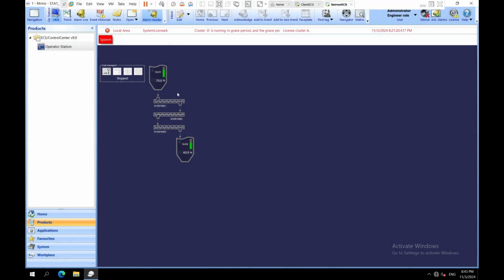The first project presented in this course will focus on a coal transportation system. The system will consist of two silos, two analog measurements to determine the percentage fill level of the silos, overflow sensors, and 3 screw conveyors. For conveyor systems, the sequence of activation is crucial.